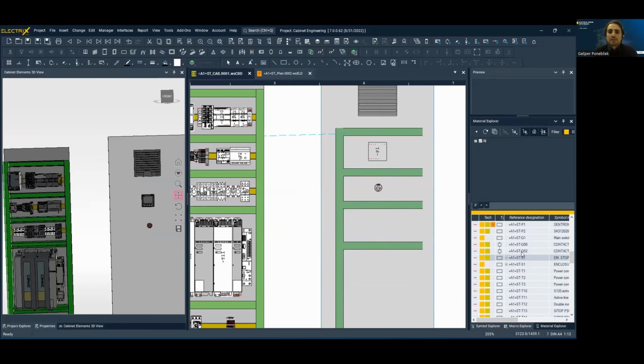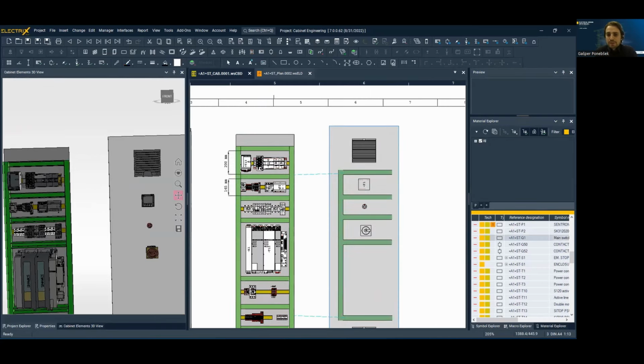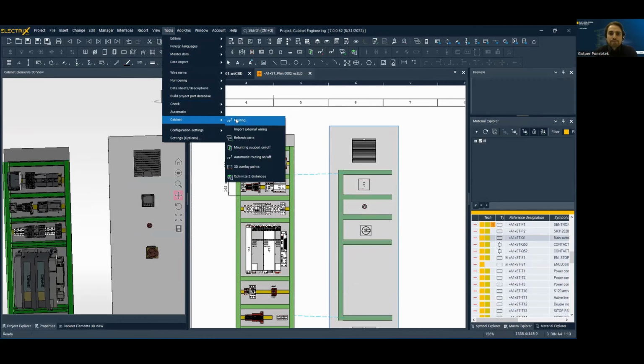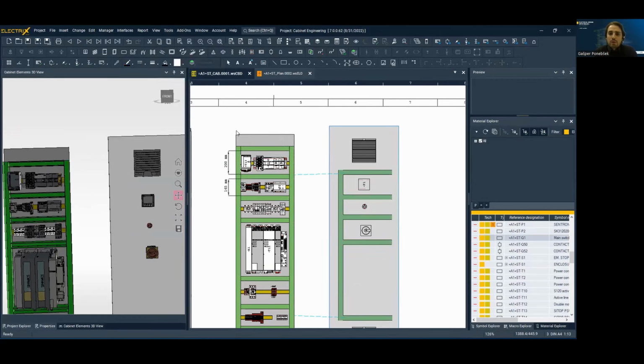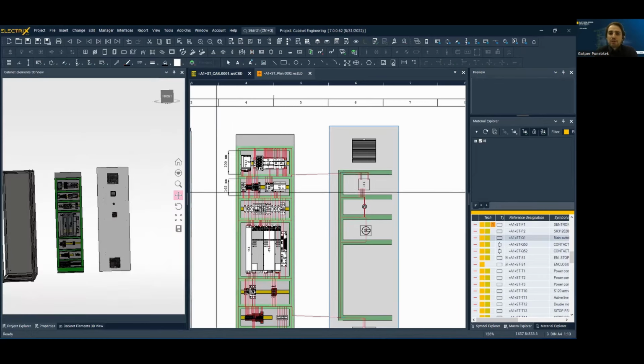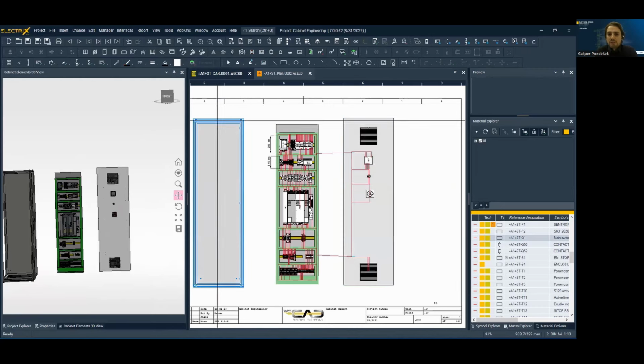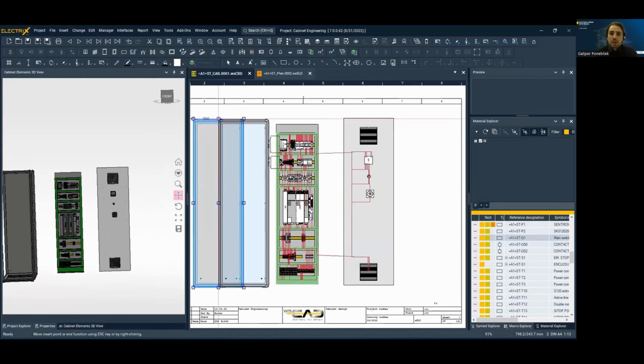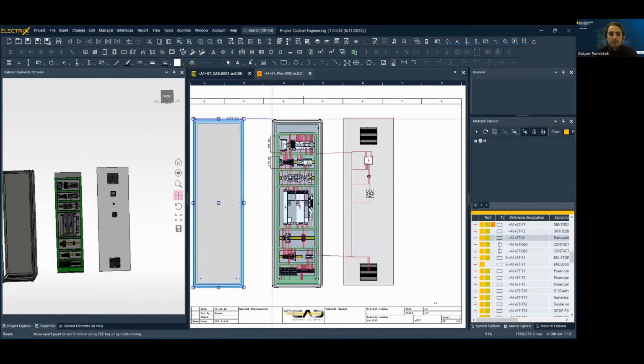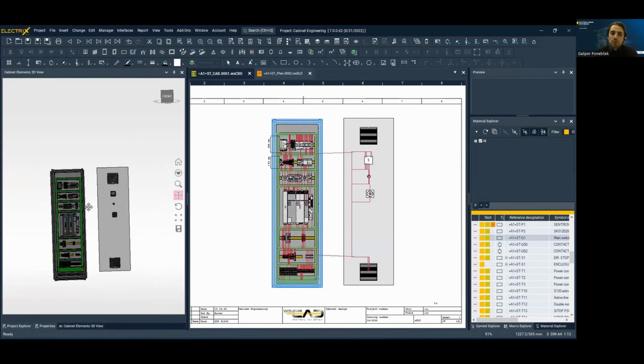But what we have to be careful, that we also insert this virtual path. This virtual path, you can see it's a dot line, blue dot line, and it's because of routing. We have to place it that when we will do right now the routing. So now we have all elements. We will do this routing, and now, yes, now the software will calculate all the length of the wires in a cabinet. You can see right now. Now we have all information about the wires from what we need, the length. So here we can just insert the mounting panel into cabinet.